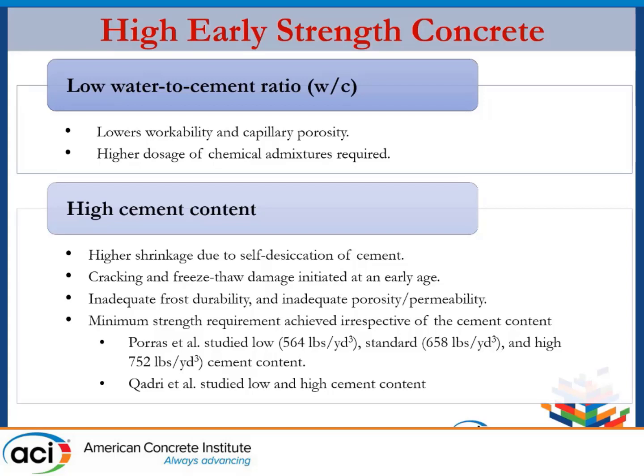That's why the research by Dr. Yadira Porez and Faisal Qadri focused on understanding whether, with different cement contents, we can still reach the minimum strength requirement. Dr. Yadira Porez focused on using low cement content, standard, and high cement content. It was observed that all of them were able to satisfy the minimum strength requirement given by KDOT, but they all still had inadequate frost durability.